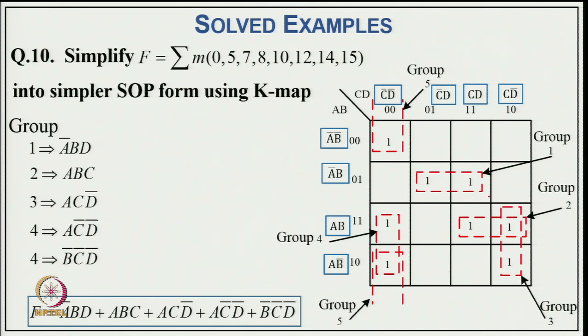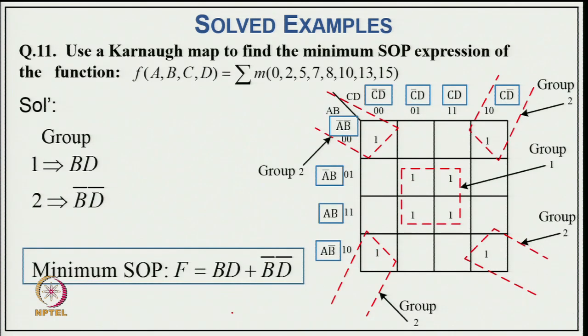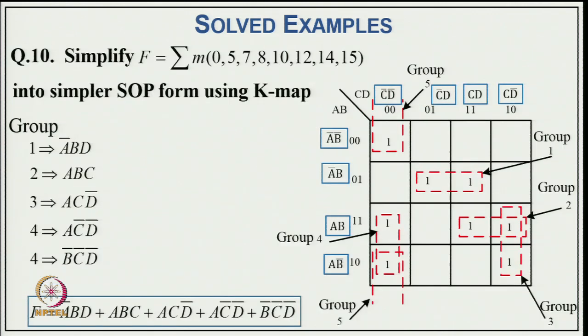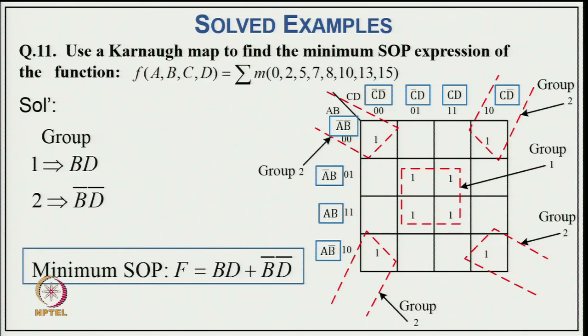Here you can call it C and D, so D is canceled out. But this is A B, and C is added with that, that is A B C. Similarly, for all 4 groups, you have a final expression. Taking the minterms, you can have f equal to the summation of all these 4 groups, which can be simplified finally in the group form, reducing the variable.